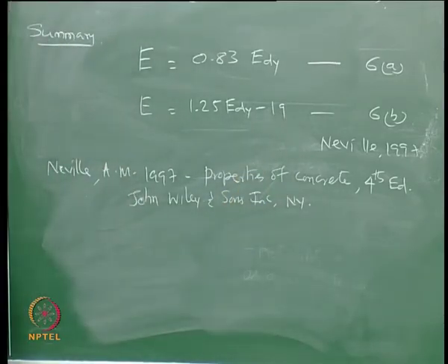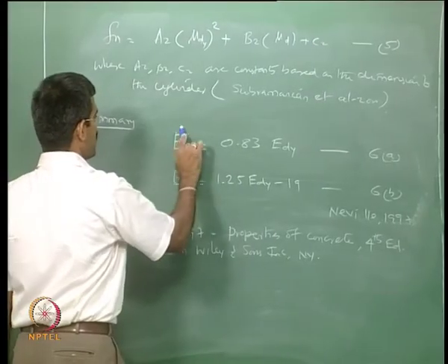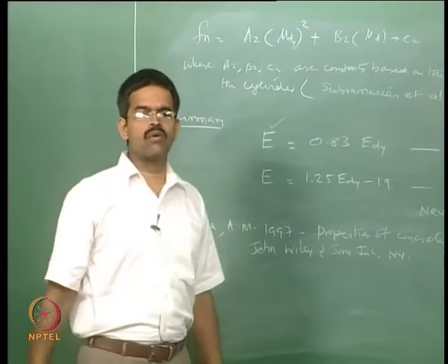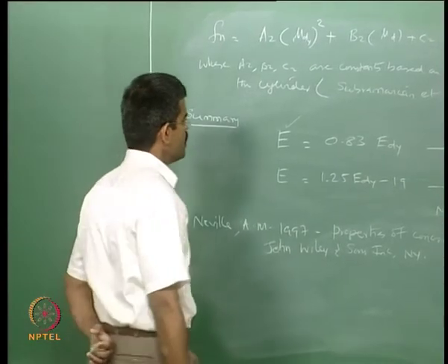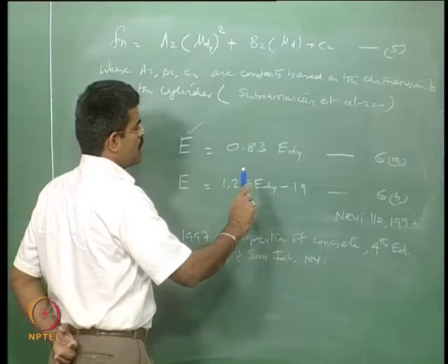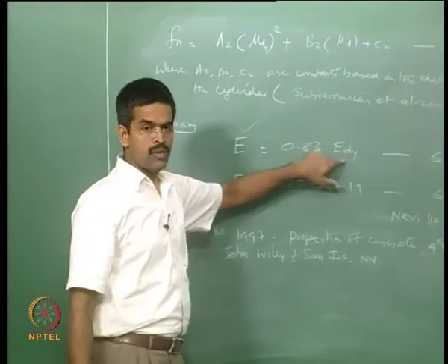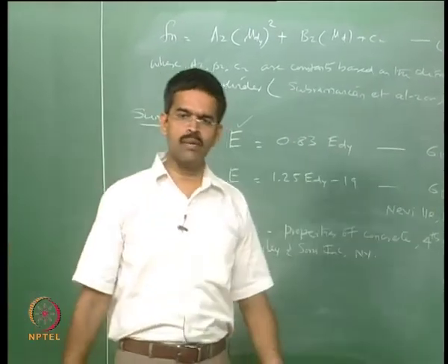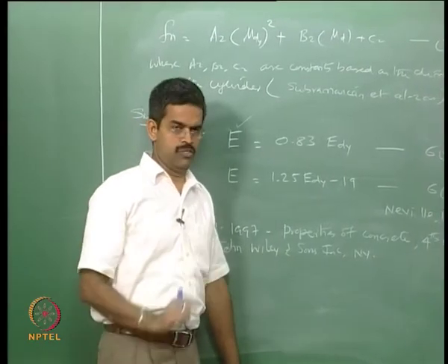So, one can see that if you are using static modulus of elasticity, or simply modulus of elasticity, in your calculations for the design or analysis, you are actually underestimating the capacity, because the modulus of elasticity of the material varies depending upon the shape of the material actually being used, the dimensions of the cylinder of the material, and the loading methodology.